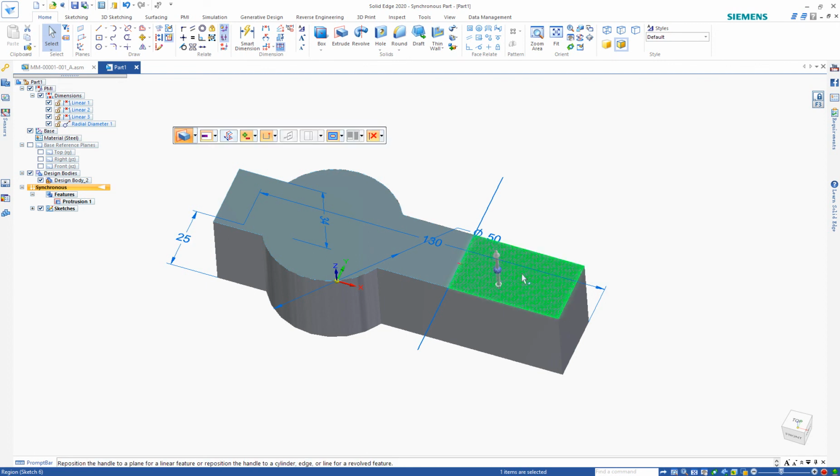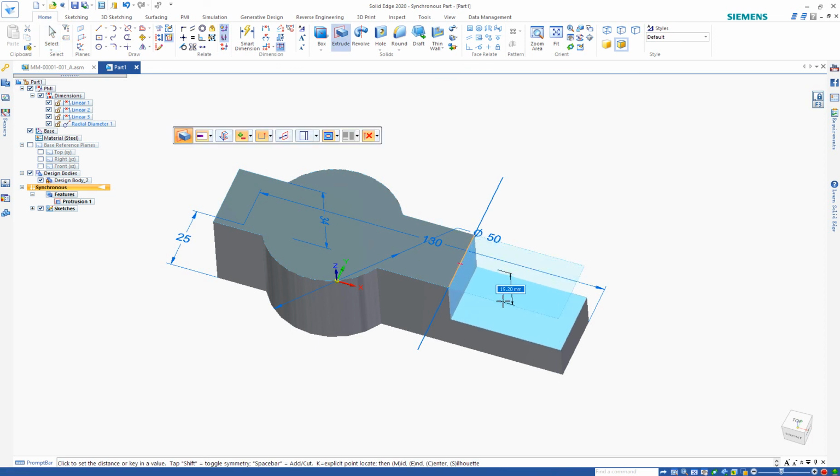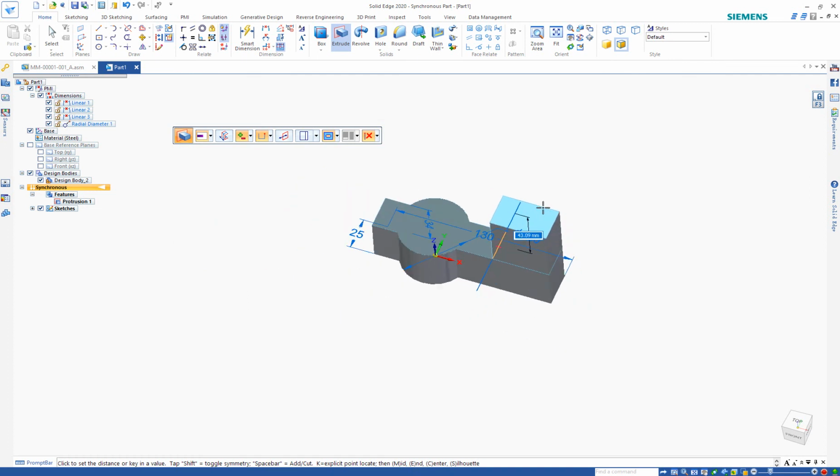So you can click on the region, and then click on the arrow to either drag down and cut it from the part, or drag up to build a fuller part. We want the total height to be 150. The base part is already 34, so we can subtract 34. Press enter.